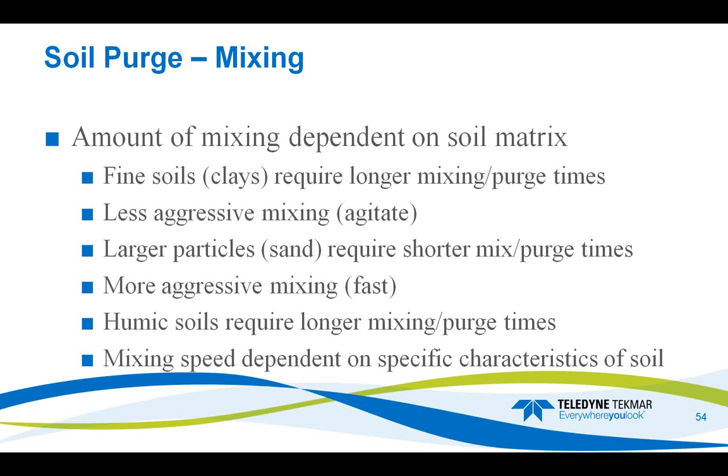We'd also recommend a less aggressive mixing, in this case maybe the agitate setting, so that we don't create a vortex and cause those clay particles to clump up and ball up and create larger blobs of clay that aren't getting adequate contact with the water. For larger particles such as sand, we don't need to mix nearly as long. We can get adequate contact with the water column to release the volatiles into the water with shorter mix times, and therefore we don't need as much purge time, so we can shorten our purge times.